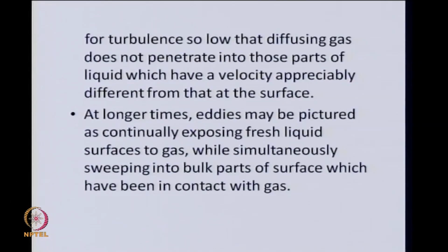If that happens, then what one has to think about is an exchange of liquid between the bulk and the surface. At longer times, we may say eddies could be pictured as continually exposing fresh liquid surface to the gas and simultaneously sweeping into the bulk that part of the surface which has already been in contact with gas for some time.